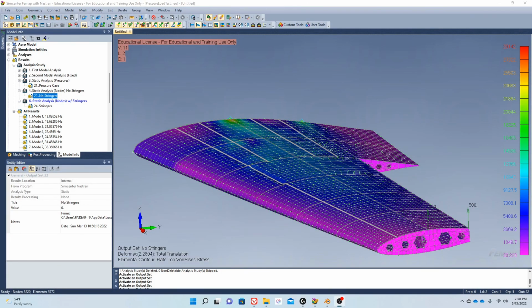That concludes this portion of the project where you set up the model and you analyze it to verify the inclusion of stringers and how they affect your structural model. Note that you can change the dimensions of everything used in this model by just going to Modify, edit your property. And if you changed one of them, it will affect the rest of the model, and you'll have to run an analysis to see the change in that.